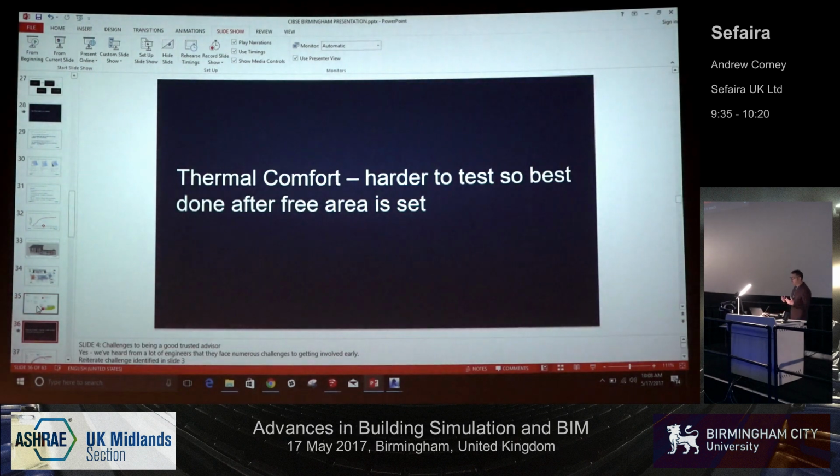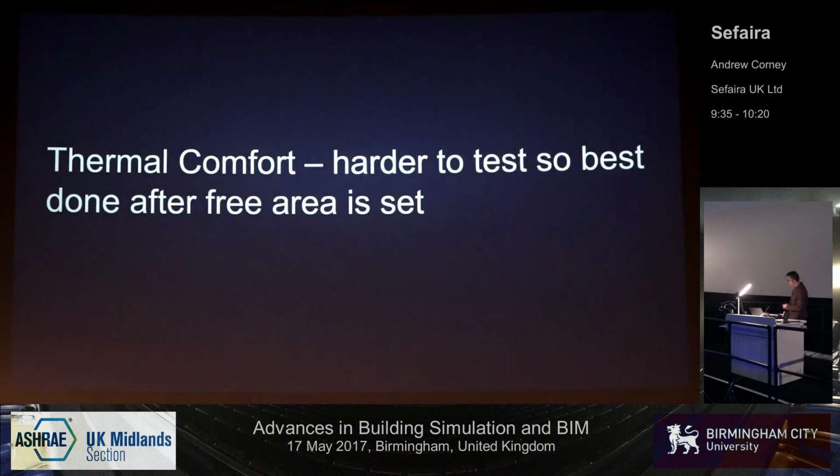The thermal comfort is a lot harder to test. Let me just see here if I can go back to the slide presentation. Thermal comfort is ultimately what you're interested in. So just because we know what the free area is and there's some anecdotal evidence that 5% free area gets you to a good place, you're probably interested in talking to the architect about shading, thermal mass, window ratio, a whole lot of other things, and how these design features are going to affect the building performance.